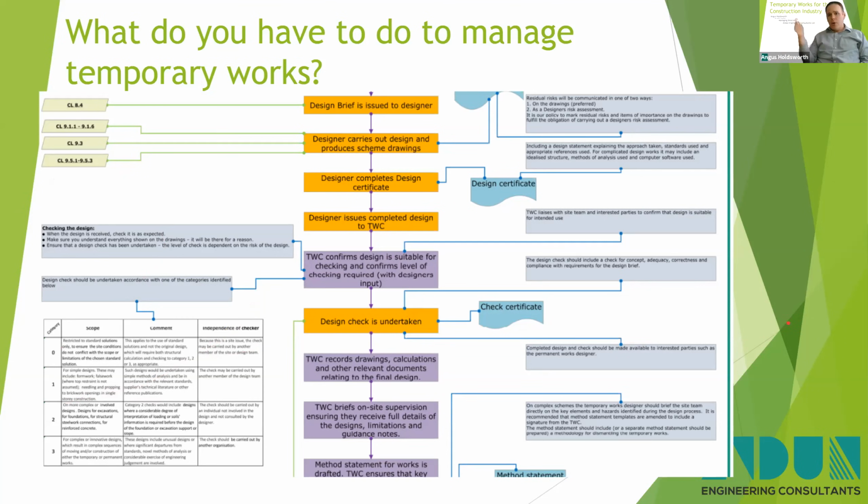If there's a note on the drawing that the designer has put there and it doesn't make sense to you, then the best thing you can do is ask a question. It could be the designer has spotted something you haven't, or it could be that the designer has misunderstood something that's on site. It's always best just to ask the question. In fact, one of the standard notes on our drawings is, if in doubt, ask. It's much easier to ask a question than make an assumption.